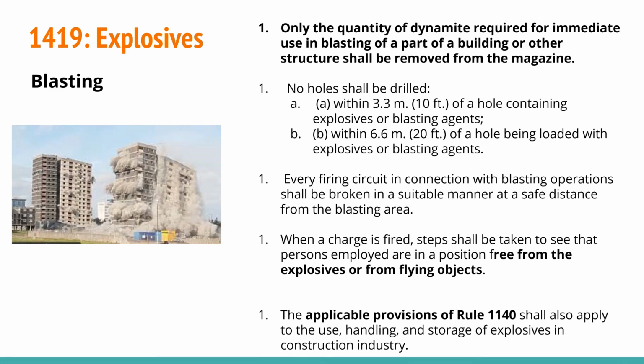During blasting or destruction, only the quantity of dynamite required for immediate use in blasting of a part of a building or other structure shall be removed from the magazine. No holes shall be drilled within 3.3 meters or 10 feet of a hole containing explosive or blasting agents. Also, none within 6.6 meters, 20 feet, of a hole being loaded with explosive or blasting agents.